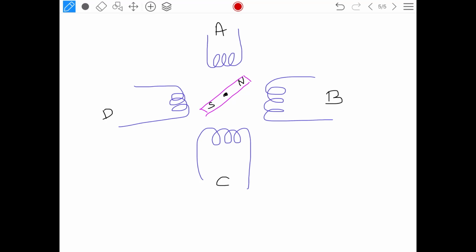First, I will energize coil A. Energizing means I am sending a high pulse, so the rest, B, C and D, are all zeros. Now, north pole is established in A, hence the rotor's north pole is repelled.